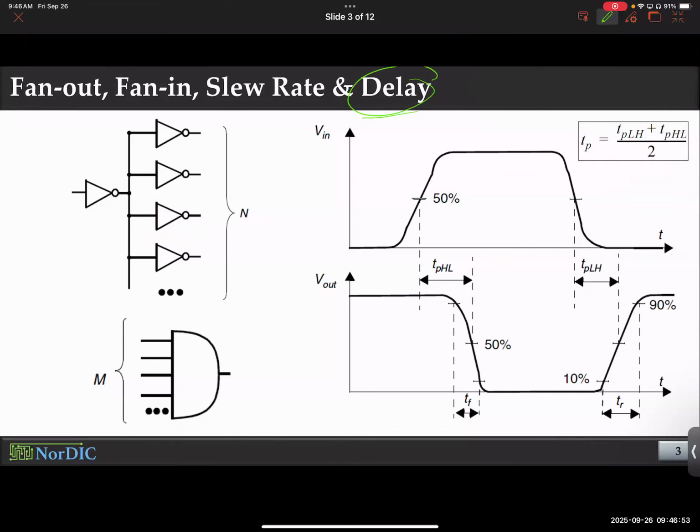So we covered the delay part, but there is another concept called slew rate. What is the slew rate? This basically caters to the question that was asked before. Why do we see this even at the input? Forget about the output, which is being created by the inverter circuit. How about the input? I am providing the input to the gate terminal of the transistors, which has a capacitor. So even if I try to change the voltage instantaneously, it will not change instantaneously, because I simply cannot change a capacitor voltage level instantaneously.